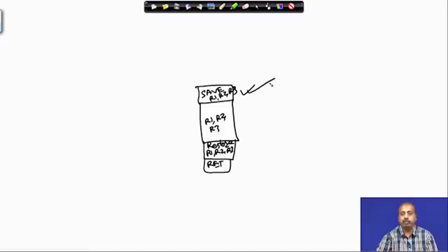Now, this is the overhead. Particularly for an embedded application, if I am working in a real time environment and that interrupt has occurred, I have to save the registers before going into the actual operation. So, that is an overhead. If I use the FIQ mode, we have a separate set of registers, R7_FIQ to R14_FIQ. If you use those registers only, then you know that they are different from whatever registers the previous user program was utilizing. So, you need not do this saving part. You can forego this saving and restoring part, and your ISR becomes much simpler.